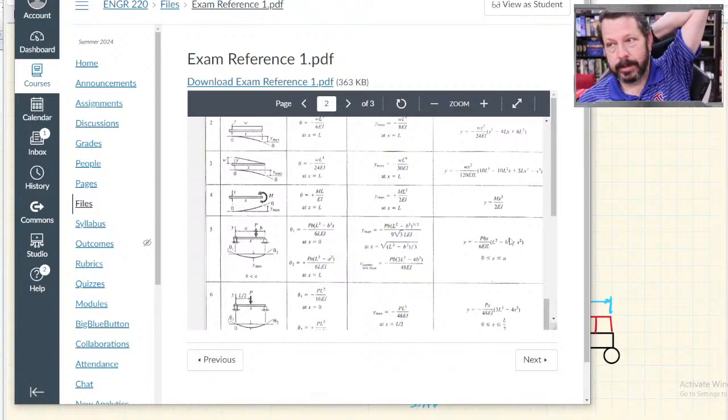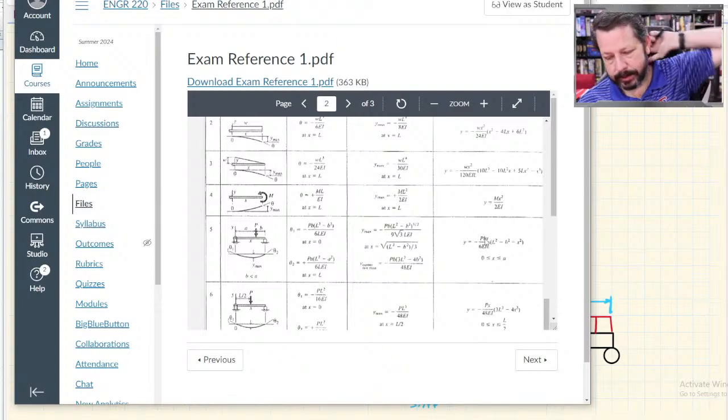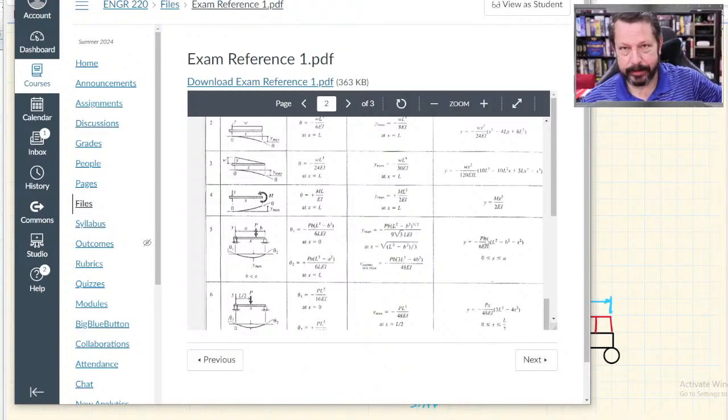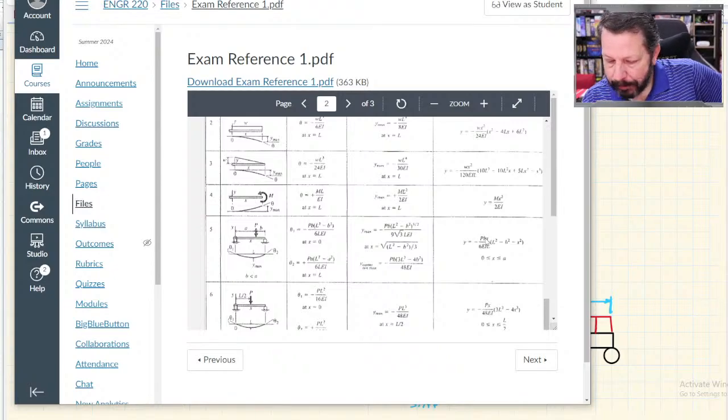So I think that probably means take both equations, get them set up to where, like this one, the x is one thing, then the x is another, so I have to deal with that. Take the derivative of that resulting equation, the two added together, set the derivative equal to 0, and solve for where that is true, and that will be the point of maximum deflection.